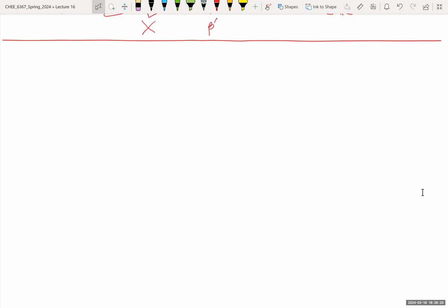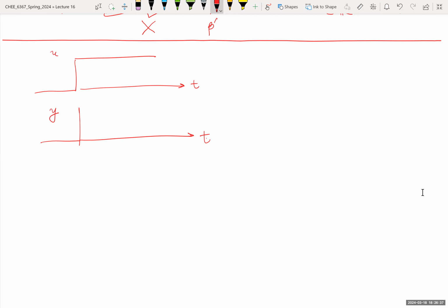So this ties with what we learned in the early part of the previous lecture, in the identification section. So we said if we have this input and we produce this output, and we make a step change here that produces something like that, the output asymptotically goes there. We can tell what is the response of the system.